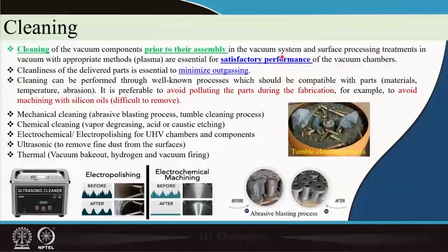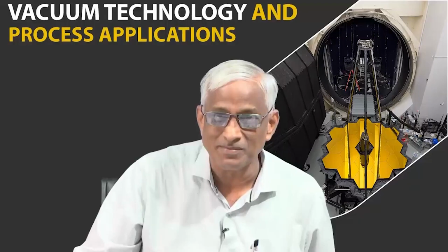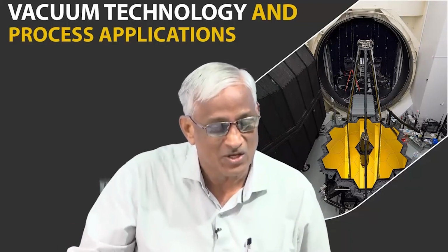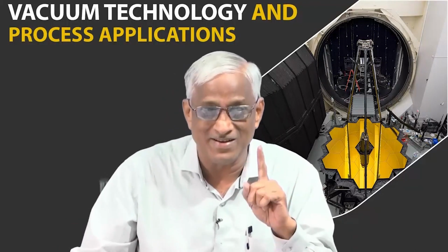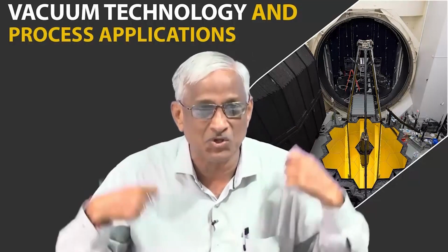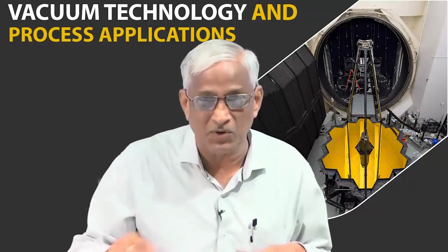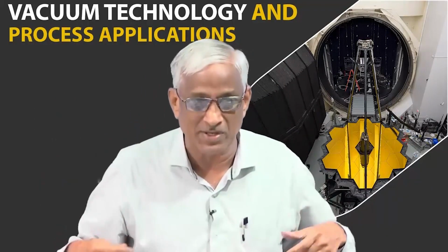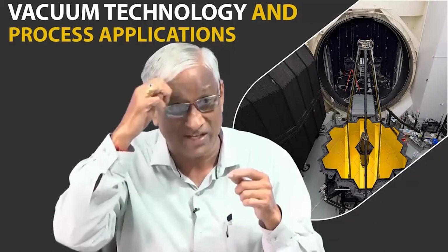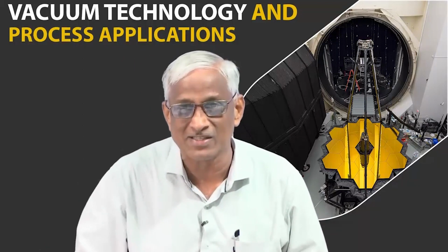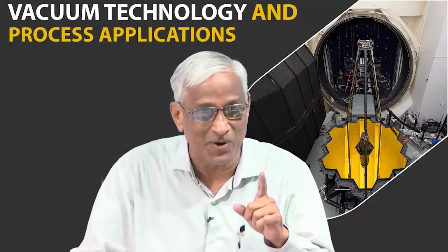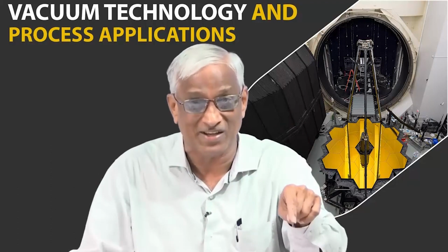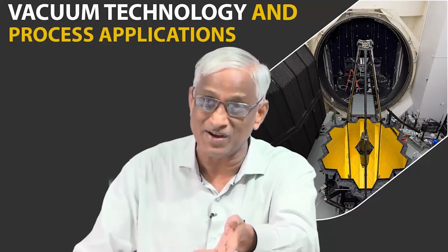Clean technologies, green technologies are the main words we are hearing nowadays. Similarly, in vacuum technology, cleaning is very important. Even the persons should wear aprons before they enter ultra high vacuum chambers. They should go through a shower room and have a drying chamber. They should not sweat. They should not be in tension. If they get tense, they will sweat, and 1 cc of sweat will create billions of cc at ultra high vacuum. So, cleaning is important, but the cleaning agent should not be left before you start operating under vacuum.